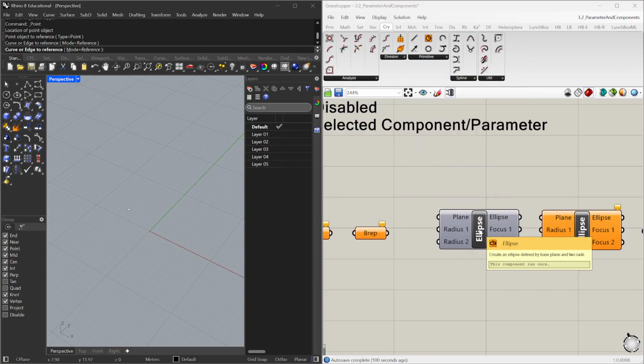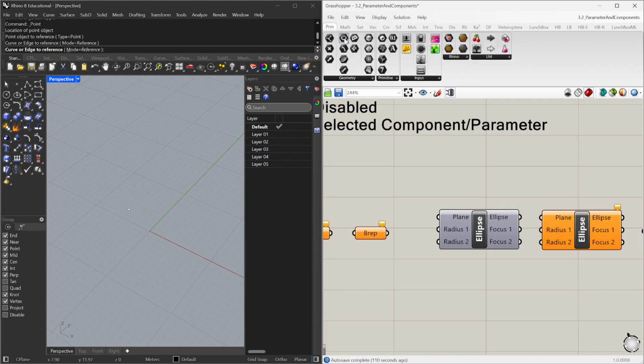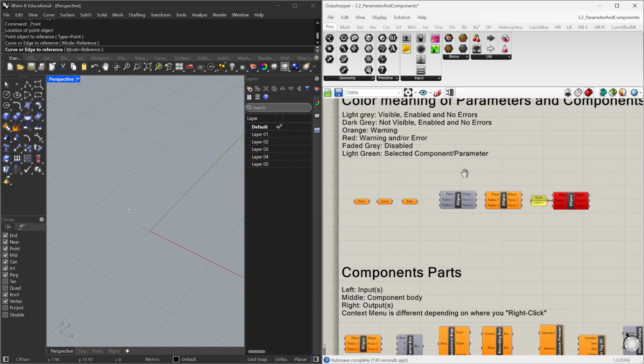So if you want to have a test of doing that, just drag a parameter on, it doesn't really matter what you drag onto here. You can just drag something from parameters onto your canvas. And if you hold Control Alt and then left click, it will show you exactly where to find that in your menu bar, which can be really useful, especially if you're downloading different scripts.